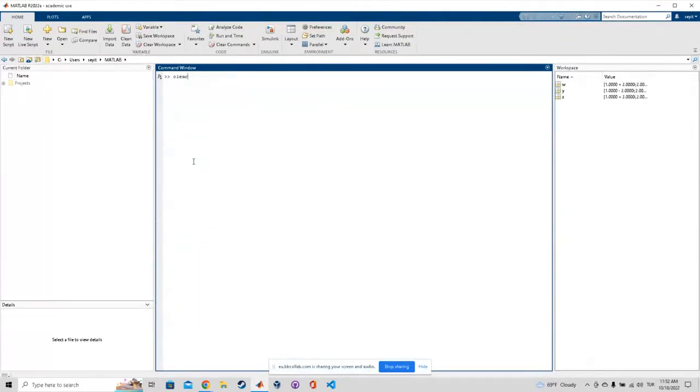Okay, let's go back to transfer functions. How do we get the transfer function of a system? Let's first define our system. We define our system equals tf, which means transfer function. Let's define our transfer function. Let's say the numerator is 1, and you put a comma, and the second one is your denominator, which is, let's say, 1 1, which is 1s plus 1, right? And then when you just hit enter, it will give your system.